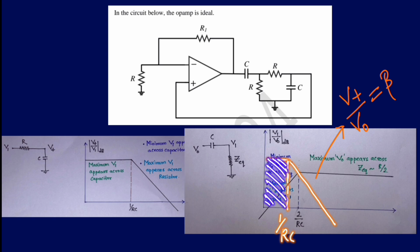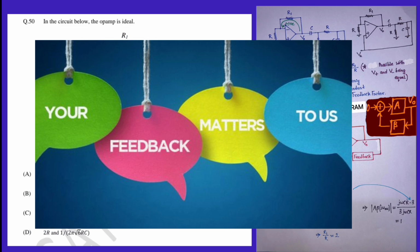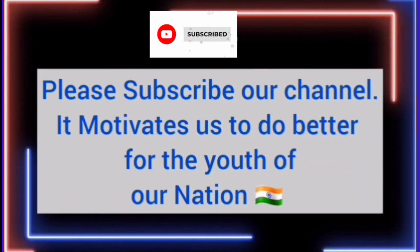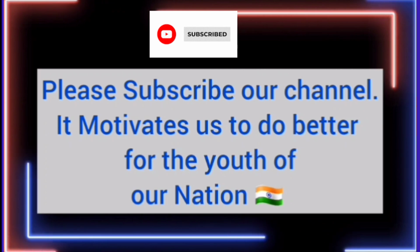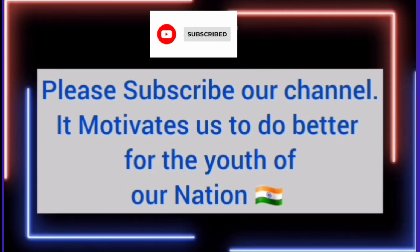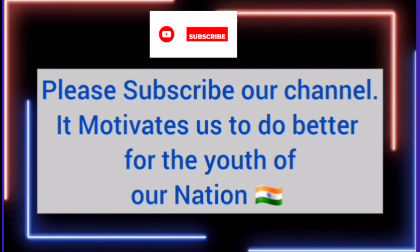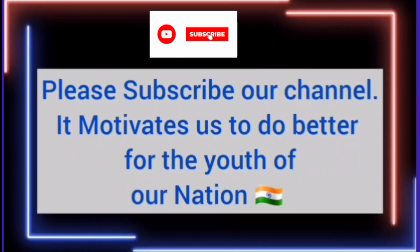Here I have made some asymptotic assumptions, because of which we are not getting two poles. Generally we get two poles when there is a second order circuit, but we are not getting them because I made many assumptions. So this process might not be efficient or might not be correct to find the correct frequency of oscillation. Okay, generally there have to be two poles, which we are not getting because of these asymptotic assumptions. So it is just another method which I have shown you, but there is no guarantee that you will be able to get a correct solution.